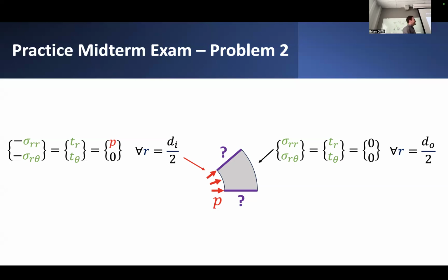No. It would make it look a little funny if it were constrained, because then it would be like you're fixing these entirely, and then this thing might bubble out, which is really not what it would have to look like if we're trying to solve the original axisymmetric problem, right? Really, we want points along this interface to just slide freely, unconstrained, such that they can displace outward radially in the same fashion as any other points that might lie interior to this circular arc.